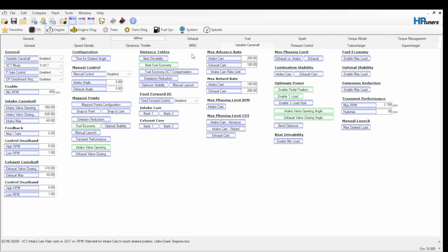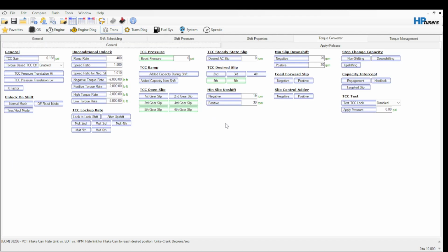And that brings us to our other point, transmission. I have seen numerous, and fell for myself, several of these terrible, terrible tuning advices. The first thing I always see: increase this boost pressure. I don't think one person that is not a transmission mechanic or an actual mechanic by occupation can tell you what that number means. And that number shouldn't matter to you unless you're doing something extravagant, because the transmission is going to tell the torque converter what the pressure should be, and it probably knows better than you. So I wouldn't touch that yet.